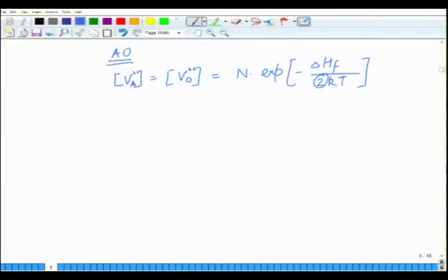So this is about the point defects discussion, that you have point defects such as vacancies and interstitials, and point defects are basically stable, equilibrium defects, and free energy is minimum at a certain concentration at a given temperature, and their concentration increases as a function of temperature. As you increase the temperature, they become more in number exponentially.